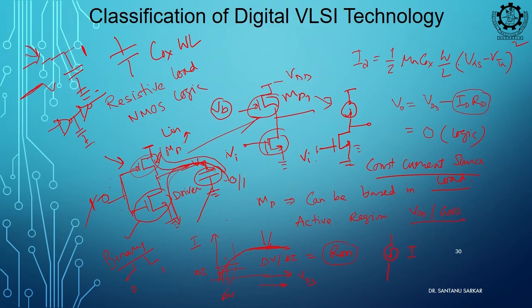In case of static, it is always connected to the VDD and ground through some strong connection. Okay. But in case of dynamic, there will be high impedance state, right. Any of the MOS will go off and the capacitor will be discharged from the VDD or ground side.